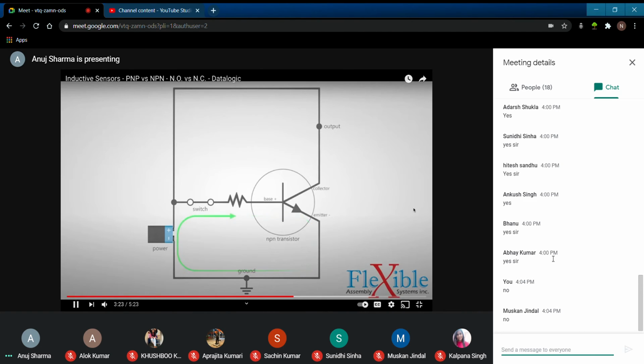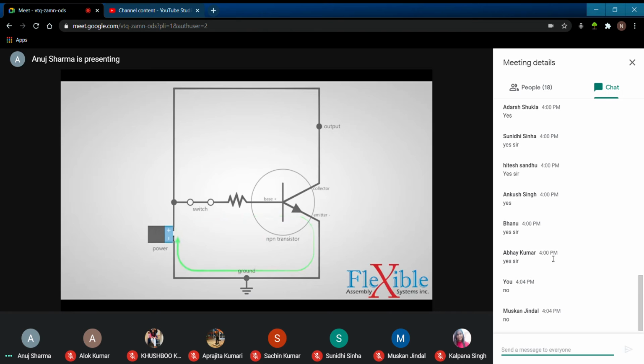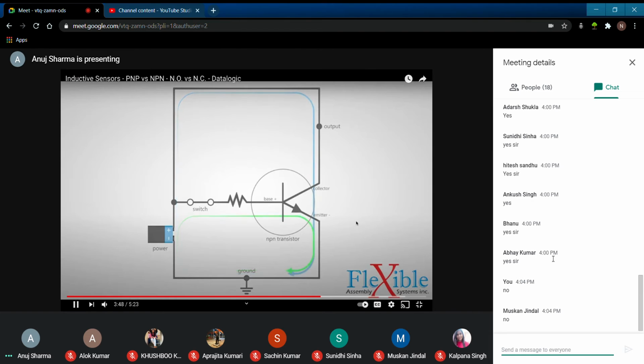Transistor on. Same current will continue to travel through the emitter, ground, back to the negative terminal to complete the low current loop. Now that our transistor is switched on, we have a larger loop that becomes active. A higher current will now flow from the positive terminal into the collector. From there, it is shunted to the emitter since the transistor is now on, travels through the ground, and heads back to the negative terminal.